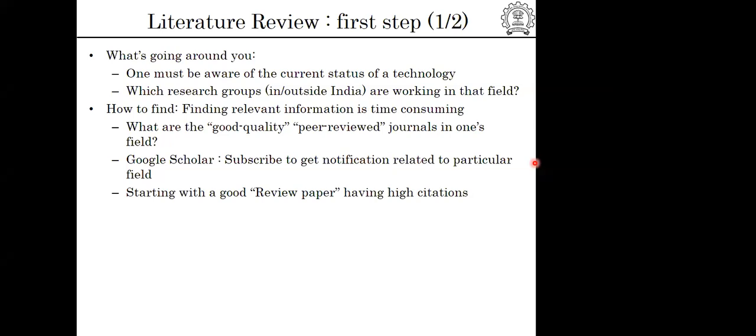Now the question is, if you want to create such micro holes, what are the challenges? If it is a traditional soft material like metal, then you can use a drilling process, right? But in the case of a brittle material, you cannot use drilling. Now the question is, what else can you use? Ultrasonic machining, abrasive jet machining, but they are not able to create such deep holes. So this is a kind of research problem.